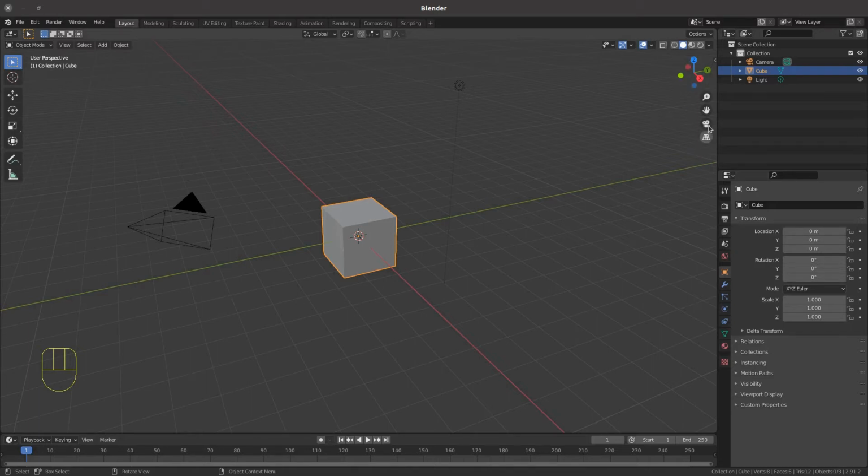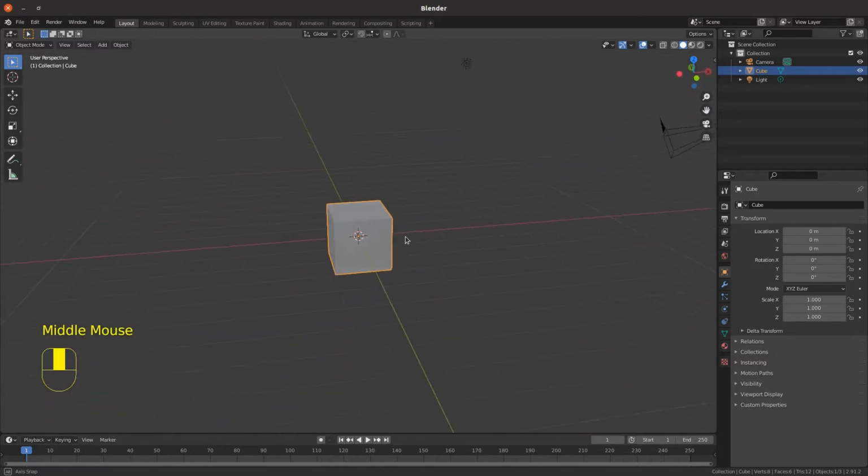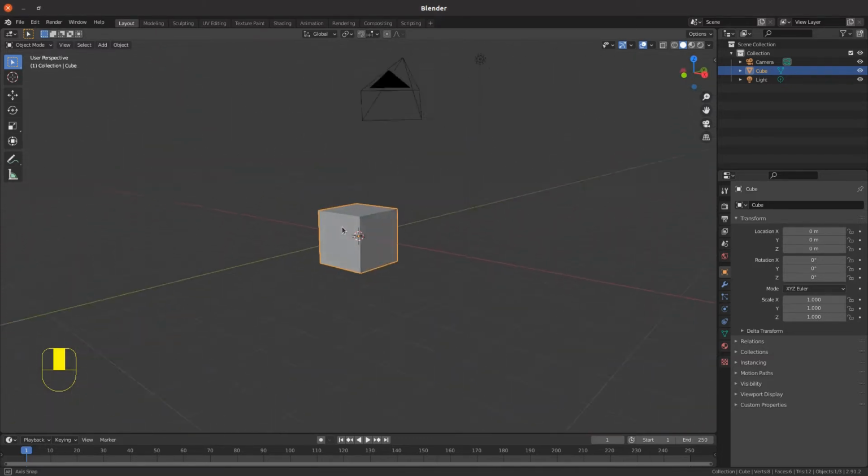So those are your main navigation gizmos on screen, but if you're working in the bottom left hand corner on a model and you want to move the view, constantly moving your mouse up to the right hand of the screen can become quite tiring, and it's not the most efficient use of your time while you're modelling. So we can look at the shortcut key options that you've got as well, or just the general mouse options. So if you wanted to orbit the view around the centre of the screen, then you simply press the middle mouse button and drag.